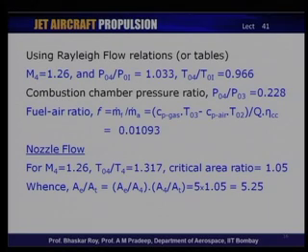Now, the flow gets into the nozzle. Now, in the nozzle, the flow is getting in with a Mach number that is 1.26, as a result of which it is already supersonic. The flow getting into the nozzle is already supersonic. Flow through the combustion chamber was already supersonic. The temperature ratio, this isentropic temperature ratio, that is total to static, at this station is 1.317.